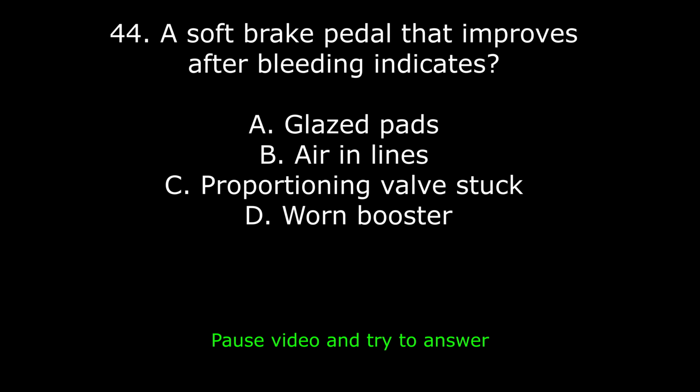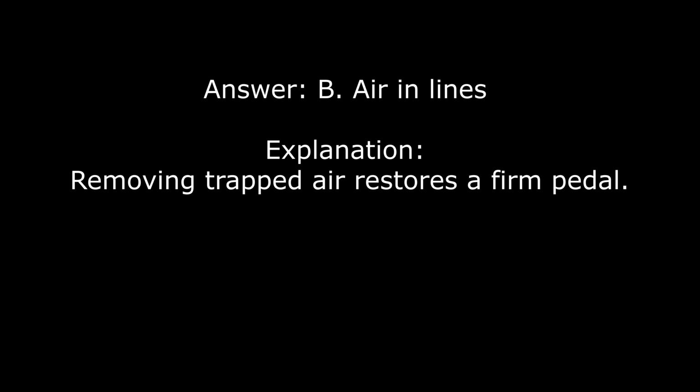44. A soft brake pedal that improves after bleeding indicates: A. Glazed pads, B. Air in lines, C. Proportioning valve stuck, D. Worn booster. Answer B. Air in lines. Explanation: removing trapped air restores a firm pedal.